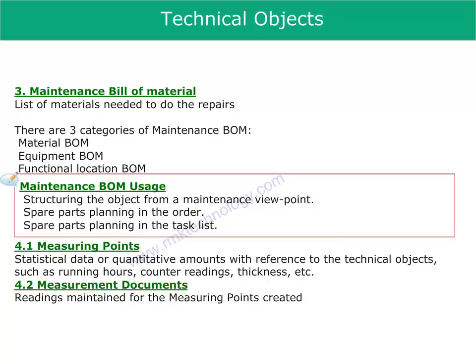You want to perform counter-based maintenance. Condition and counter-based maintenance tasks are forms of preventive maintenance. Generally, these tasks should reduce the number of breakdowns for your objects. In the case of counter-based maintenance, maintenance activities are always performed when the counter of the technical object has reached a particular counter reading, for example, every 100 operating hours.